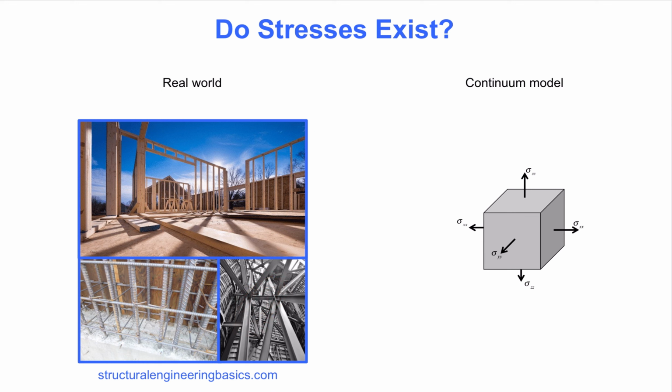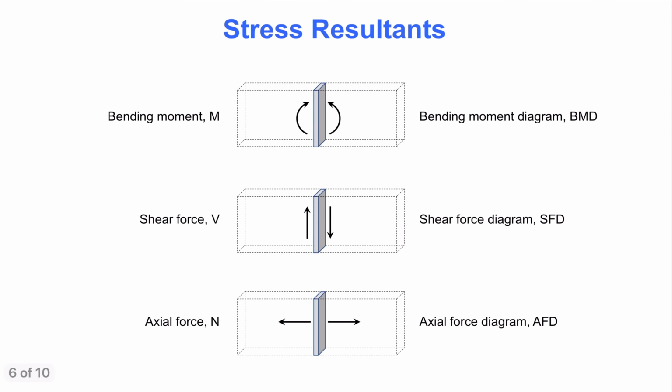The answer is that it is most definitely useful, for several reasons. First, the concept of stress opens up the possibility of establishing mathematical equations for equilibrium, material law, and kinematic compatibility. Second, the concept of stress expresses an average of the forces that act inside small portions of a material. That last point is better understood on the next slide, where stress resultants inside a beam are visualized.